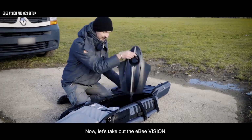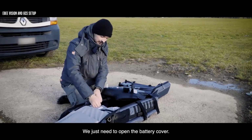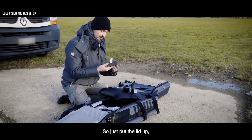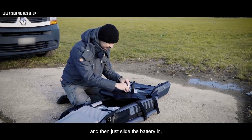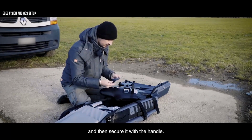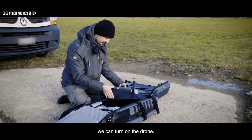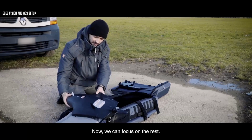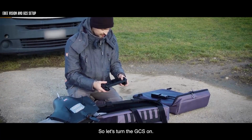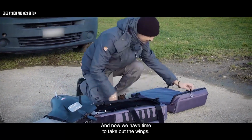Now let's take out the eBee Vision. We just need to open the battery cover, take one battery. So just put the lid up, and then just slide the battery in, and then secure it with the handle. And now we can close it, and with a long press we can turn on the drone. Now we can focus on the rest, so let's turn the GCS on. Okay, and now we have time to take out the wings.